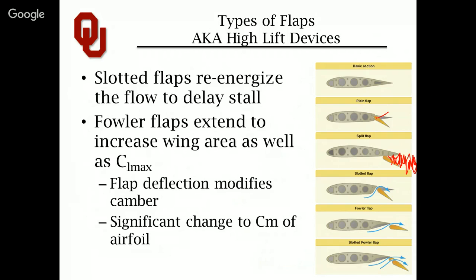And what really happens when you look at flaps, slats, all these different types of leading and trailing edge devices we're discussing now, when you look at them in a real flow scenario, they work great until you start separating the flow due to deflection. You can't deflect these surfaces 90 degrees straight down. You can't put a plain flap straight vertical and expect the flow to remain attached to it, turn that 90-degree corner without issue. No, I mean, the boundary layer will separate.